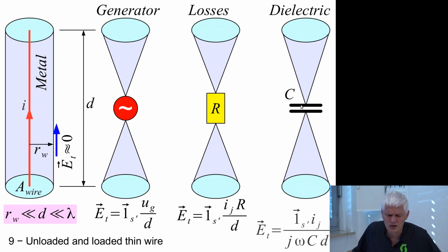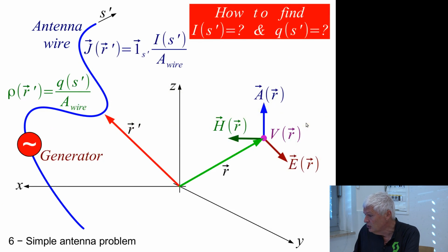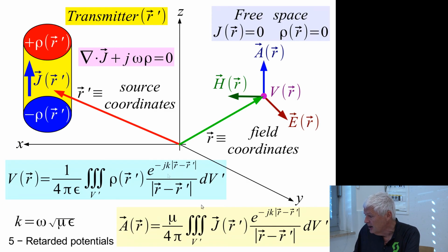We are not usually going to put that many capacitors inside the antenna. Sometimes we need capacitors for impedance matching, like a gamma match circuit. But for us it is much more important that in this way we can simulate dielectrics, because the solution of the retarded potential only works in homogeneous space. So epsilon and mu have to be constant all over the place.